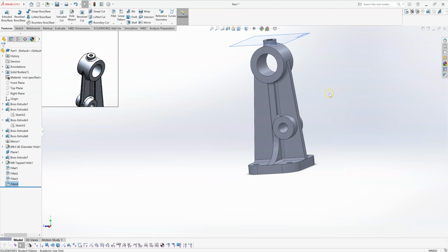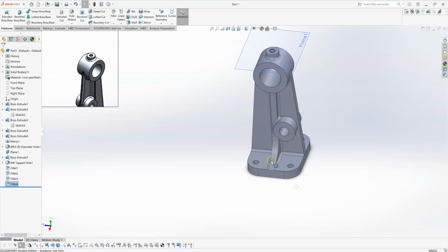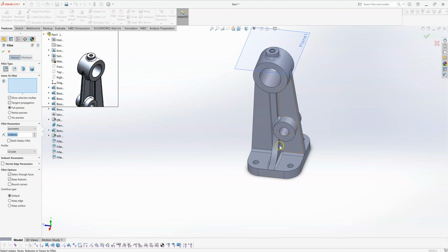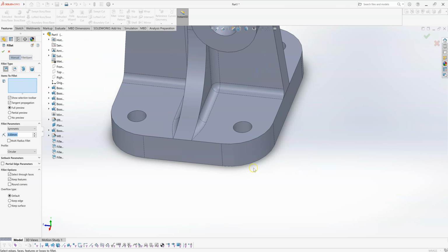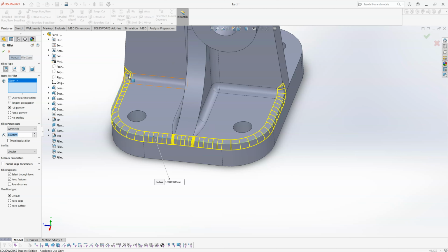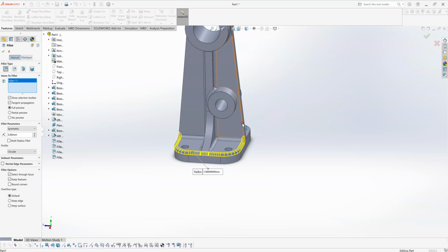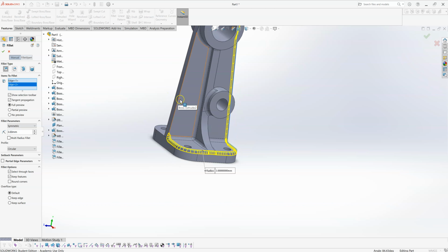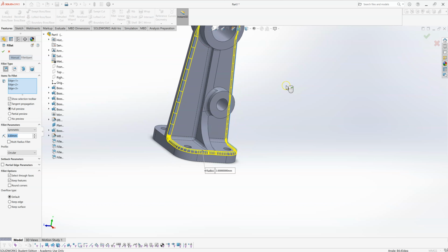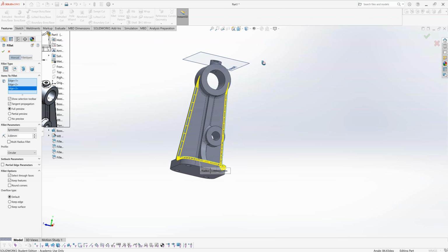Okay, that is the internal fillets. The other thing then are the rounds, the external fillets. So if I create another fillet feature here, and the items to fillet, if I pick an external corner, it'll put that in as a round here. So every edge that is connected in a straight line to this edge here, like that. And again, I would say put these into a few different features. So I'm going to do, let's say, all these external ones in this loop, like so.